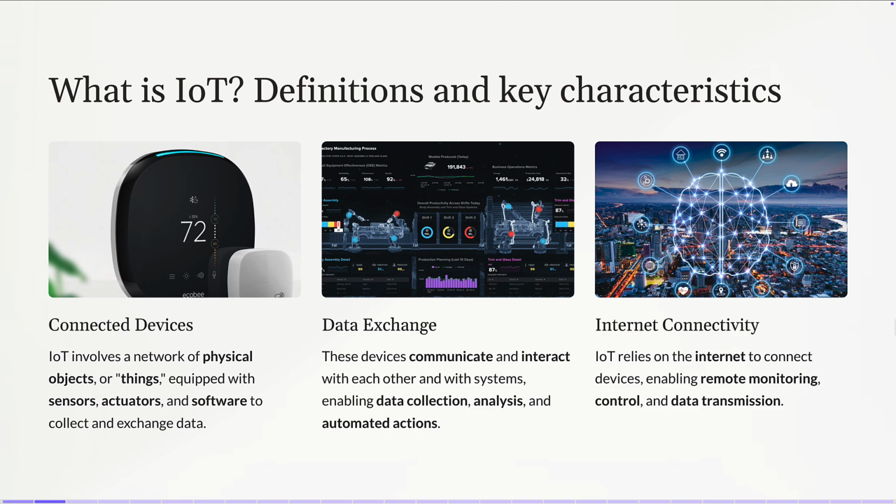This is the acceleration sensor. It can measure the acceleration in different directions, X, Y, Z. You know that the motion in space has 3 dimensions, X and Y and Z. Okay, so it can measure your acceleration, and based on this, we can use some, for example, machine learning technique or AI technique to transform this raw data based on the pattern into a classification of activity. So we can know whether you are, for example, sleeping, whether you are running, whether you are moving slowly or walking, and different type of activities.